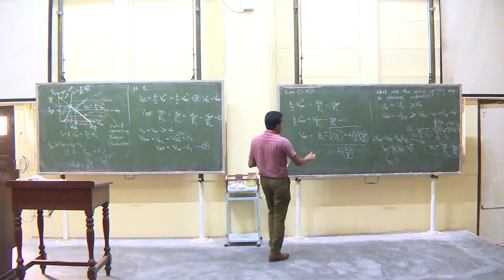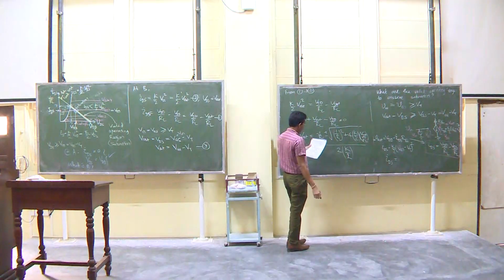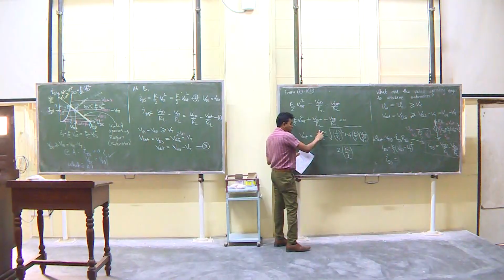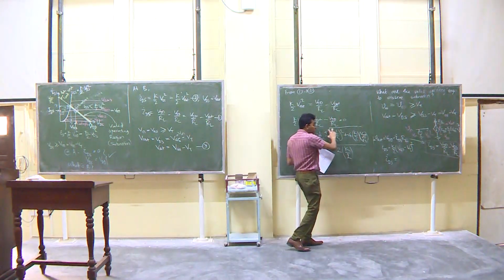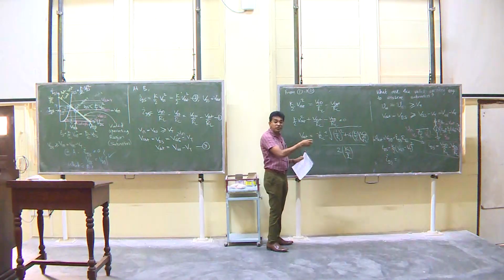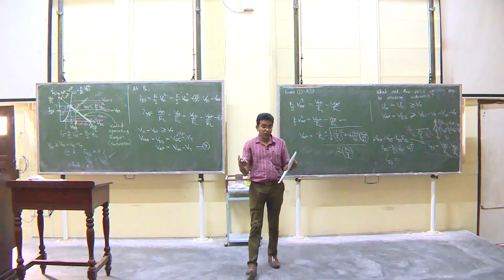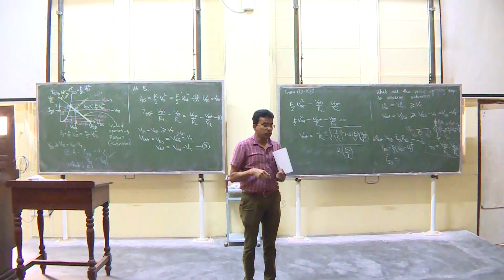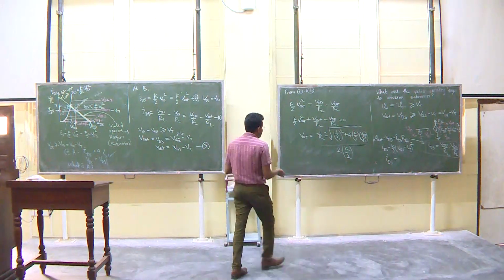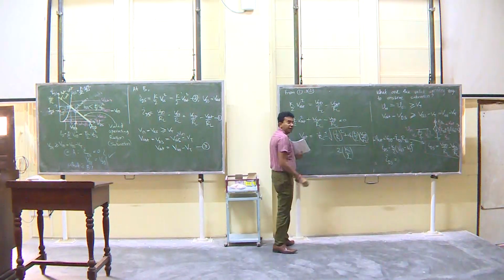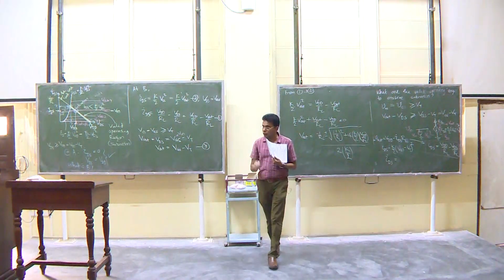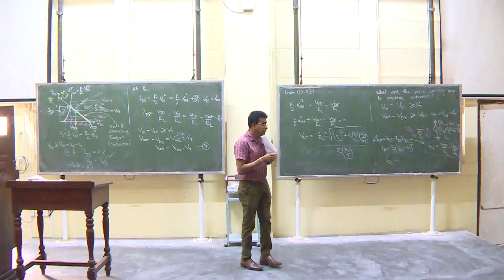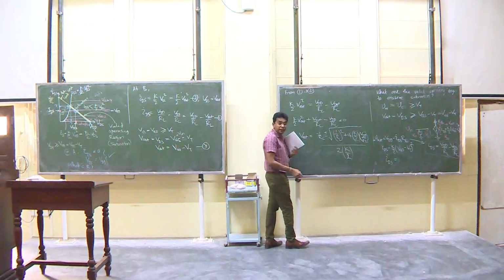So, we know this part is negative because RL is always positive. So, therefore, this part is negative. If this part is also negative, V out becomes a negative voltage, which is impossible because we have to work in the positive region because I have input as a positive voltage. So, therefore, this negative sign will not give me a valid answer. So, the only valid answer in this equation is this positive sign. It has to be there.